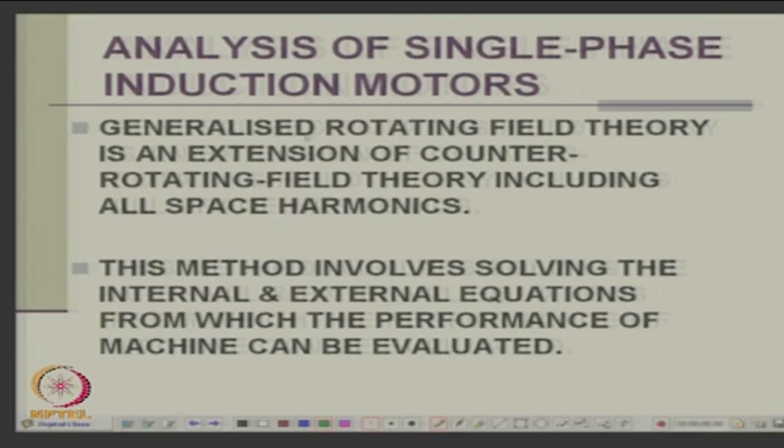Now, this generalized rotating field theory, what we are now going to discuss, is an extension of the counter rotating field theory, which includes space harmonics. So, what we are trying to say is there will be forward fields and backward fields, by the fundamental and also by harmonics.